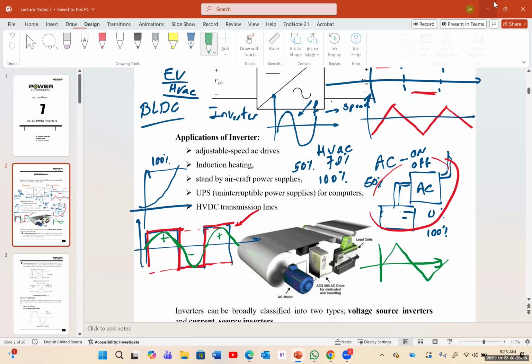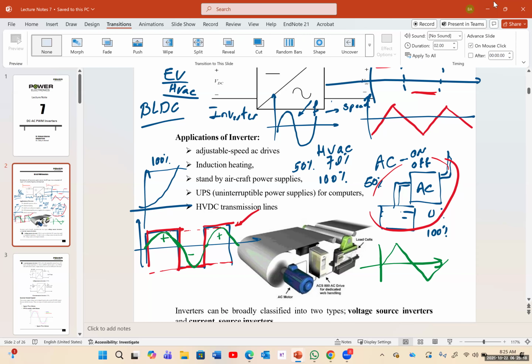If not, it's okay when you want to connect electronics, because if you connect your laptop, for example, to this inverter, the laptop again wants to convert the AC to DC, so it goes through a rectifier. So it doesn't matter. Actually, the square signal is better for it because you're going to have less ripples in the output. But if you want to run a motor and anything that runs on AC, this may cause a problem.